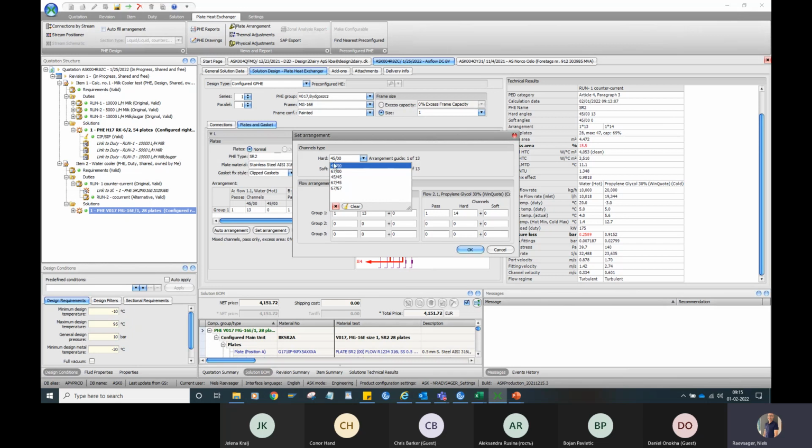So this is a mix combination here, mix here, and straight long, mix again, and straight soft. So you got many possibilities for plate angles on this specific plate type. But always use the guideline here. If you have entered in a realistic pressure drop, and of course a realistic duty here, then you can rely on the guidelines that it comes up with here on this specific type of heat exchanger. So keep it as it is.